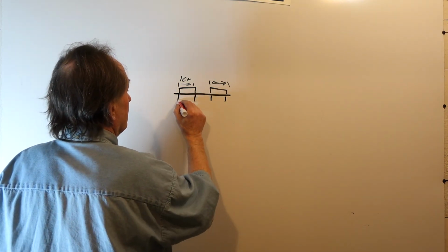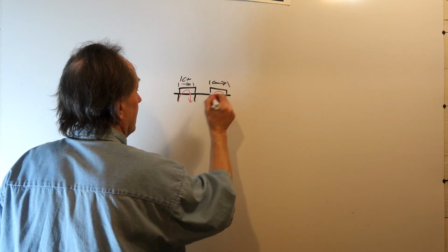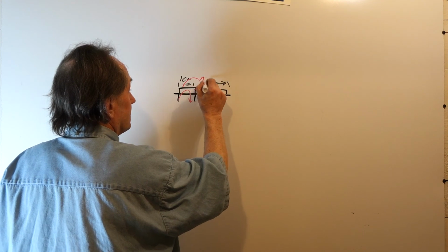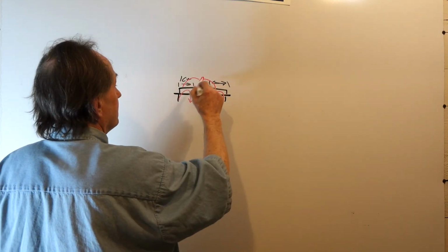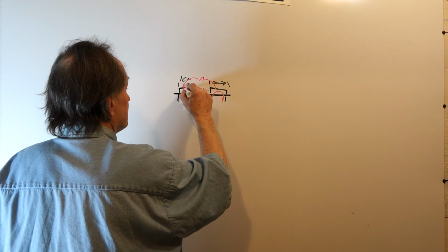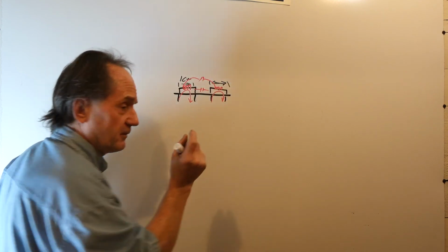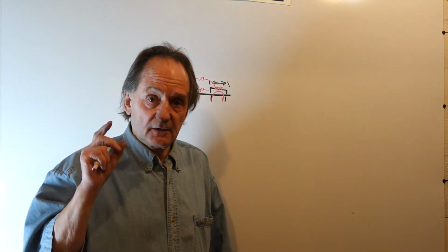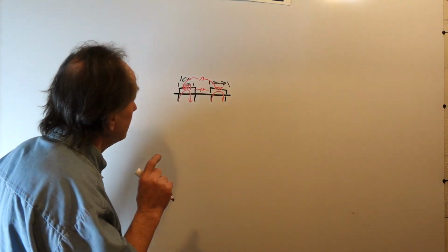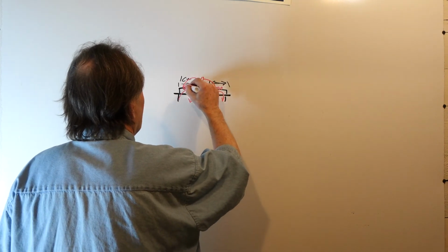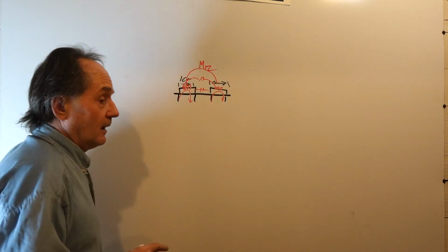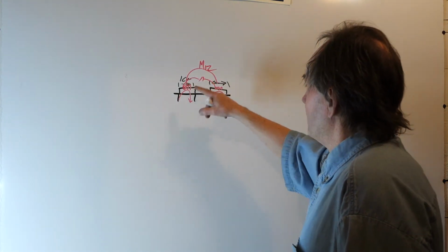There's current flowing through these relay contacts, and you have stray capacitances that couple. You also have mutual inductance, self-inductance on each of these. Even though they might only be a centimeter in length, they have self-inductances on the order of nanohenries that you have to worry about. And you have mutual coupling, mutual inductance between them. That's also down in the nanohenry range that you have to worry about.